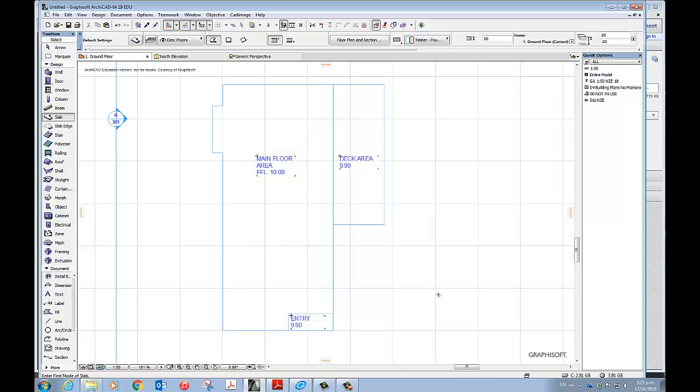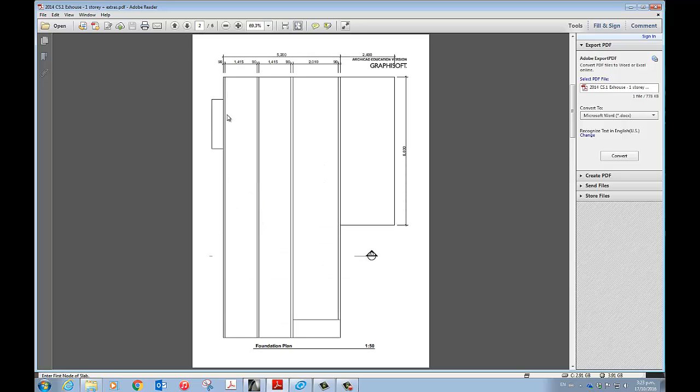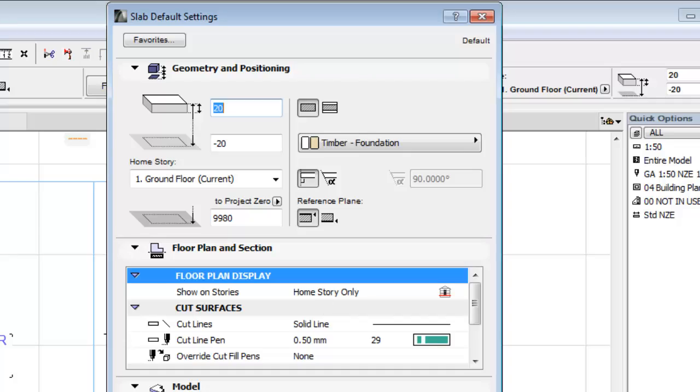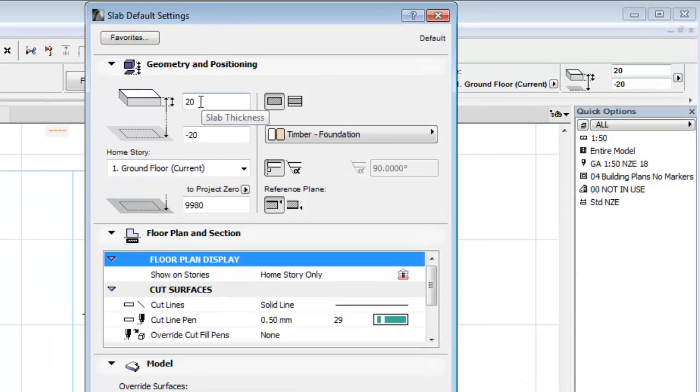Next thing we'll do is the joists, and because my colleague has already indicated that the bearers are going vertically, the joists will be going this direction. I'm just going to estimate the sizes and estimate the centers, so you cannot use the figures I use for our major project house. Slab tool again. I will change the color of the timber just to make it stick out. The depth of the joists you will have worked out from 3604. I'm going to just put them as 90.